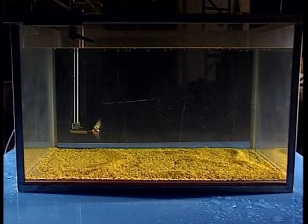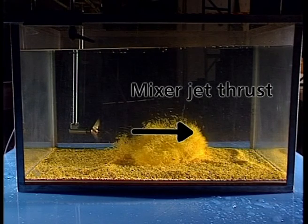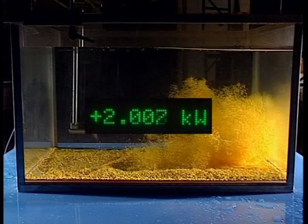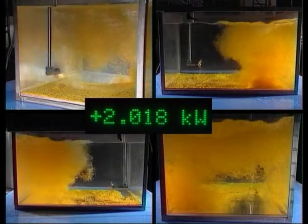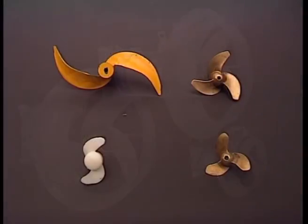The efficiency of an agitator is the relationship between the thrust produced and the power consumed. A more efficient agitator will have a higher ratio between the delivered thrust and the power consumed. The efficiency of an agitator is dependent on both the motor efficiency and the hydraulic efficiency of the propeller.